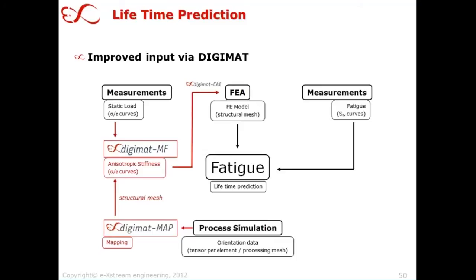And what we have on the left side is basically the workflow, which I have talked about on the previous slide. So it concerns the mapping of the fiber orientations, taking into account high-quality anisotropic material model, and all that goes into the FEA solver. So in principle, the predicted stresses from this approach are now accurate and based on anisotropic material properties.